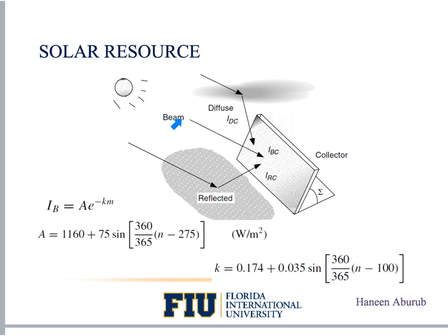Now the solar collectors that focus the sunlight usually operate on just the beam portion of the incoming radiation, since those rays are the only ones that arrive from a consistent direction. Most photovoltaic systems do not use focusing devices, so all three components, the beam, the diffuse and the reflected, can contribute to energy collected in solar PV.